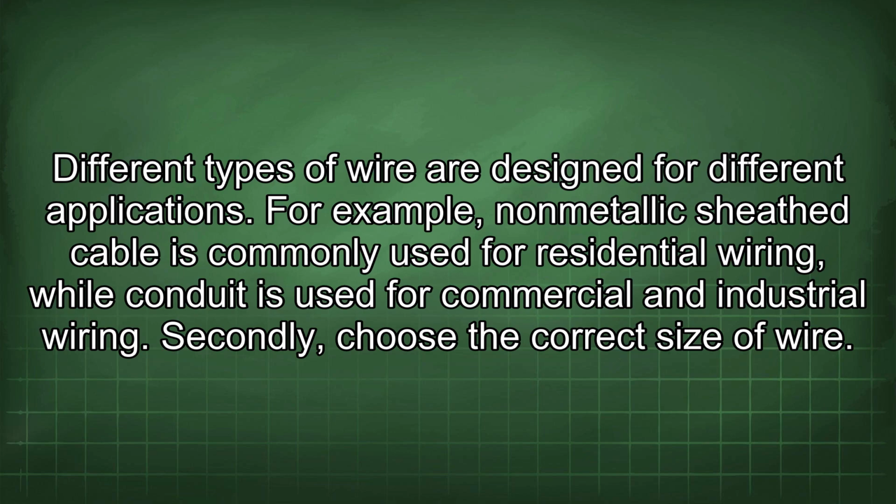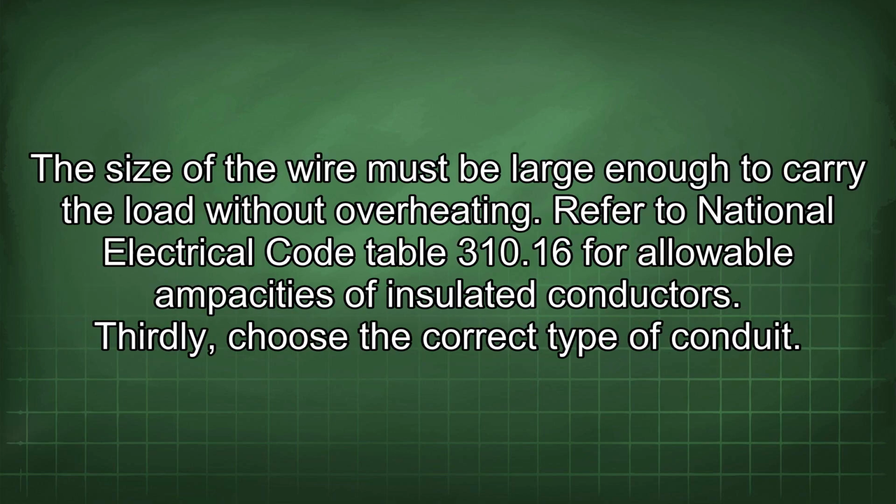Secondly, choose the correct size of wire. The size of the wire must be large enough to carry the load without overheating. Refer to National Electrical Code Table 310.16 for allowable ampacities of insulated conductors.